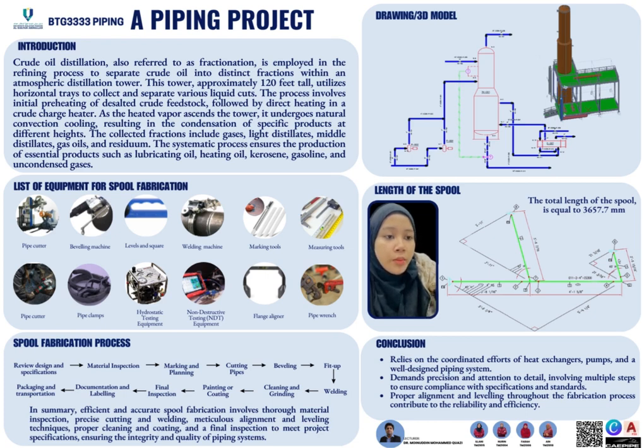On pipe 1, it has two joints, so the total root gap for pipe 1 is equal to 8 mm, and the width of the gasket according to class 300 is about 3.3 mm. So the total length of pipe 1 is 766.9 mm.